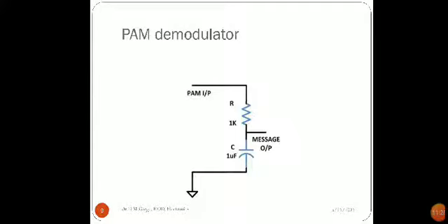So for a higher modulating signal, higher power will be needed. For a lower modulating signal, lower power will be needed. So power goes on varying and higher power also will be required. Another thing is that as the information is stored in the amplitude of the pulses, noise immunity is less. So these are the disadvantages.